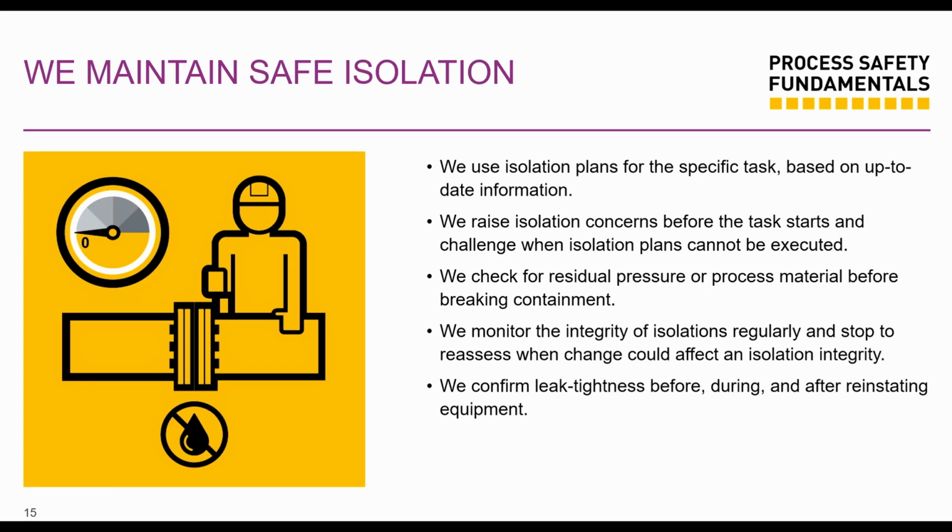It's locked. It's tagged. Your LOTO procedures. Are you locking out? Are you tagging out? Because hey, you're working on this section of the plant, and then someone is working on another part, and you believe, hey, I closed the valve, but you didn't lock it. But what if the person working on another side of the plant believes that this valve that's 500 meters away needs to be open, and he opens the valve and it affects you where you're working. So if you've locked it out, the person would know, hey, someone is actually working there, maybe I shouldn't manipulate this valve. Or they would come meet you and say, hey, what are you doing? Try to find out why that lock is in place. You're using it to save your life.